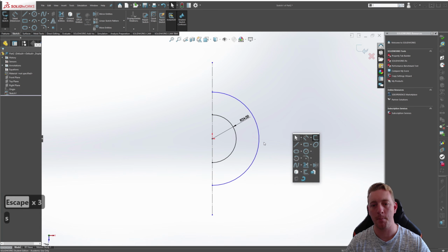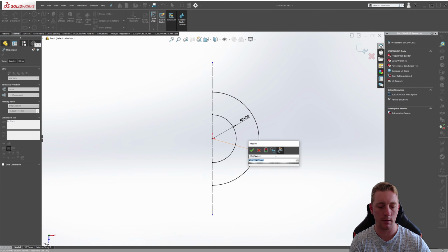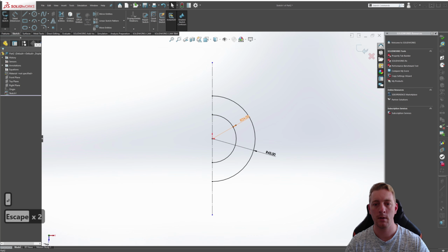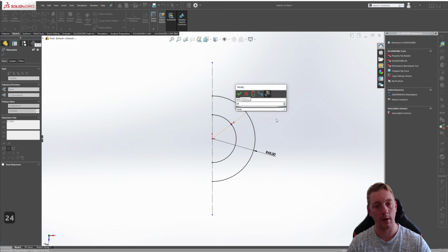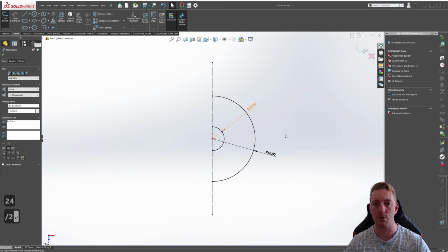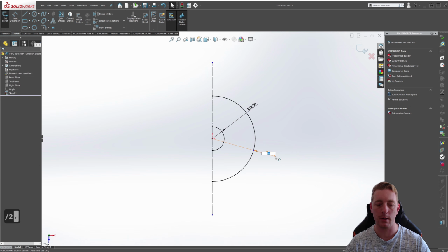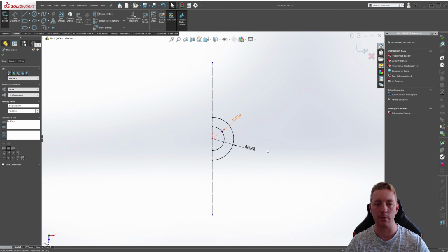And this is going to be our medium point. And this one is 43. And something to keep in mind is that the dimensions we have on screen are diameters, and these are radiuses. So one way of doing that is we can say 24 divided by 2, which will give us an actual radius instead. And this one is the same, 43 divided by 2. So that will give us a proper radius instead of the circumference dimensions that we have on the working drawing.